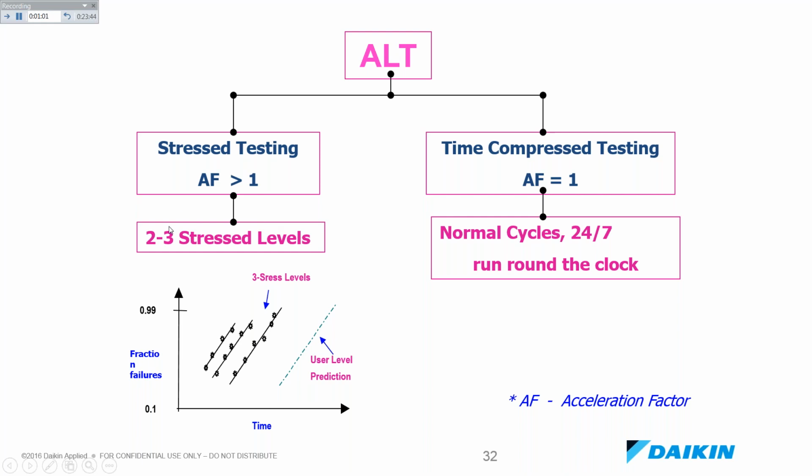For stress levels, you like to have about 3 levels of stress testing, and you allocate to different samples. Dr. Meeker recommends 1 to 2 to 4 sample size allocation. Of course, say you put 7 here, you put 14 here, you put 28 here. You put more at the lower stress level because fewer will fail there, and you put less at the high stress level because all fail. Those are a glimpse into the accelerated life testing levels.